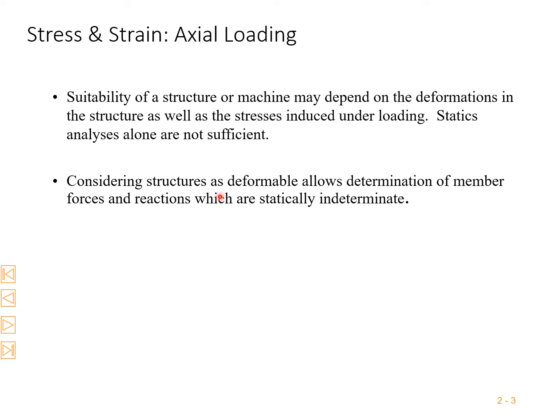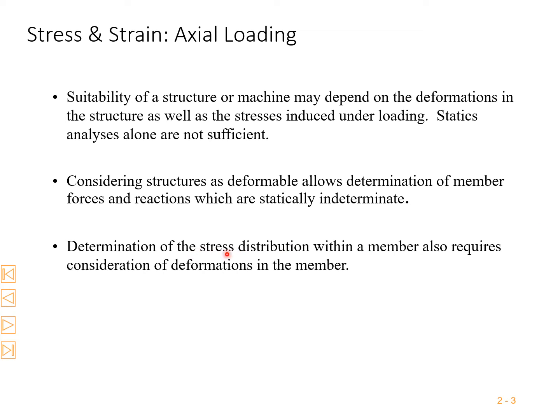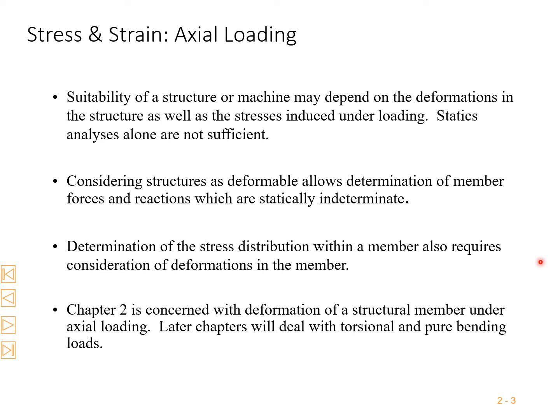If you apply any load on a particular structure, there will be a deformation. So we need to find the internal forces and reactions, in some cases for statically indeterminate structures. Determination of stress distribution within the member also requires consideration of deformation in the member. For example, to determine how the stress is distributed within a member, we need to understand how the deformation in the member is happening. In chapter 2 we are concerned with the deformation of a structural member under axial loading. If you apply an axial load, how the structure deforms, that we will study.